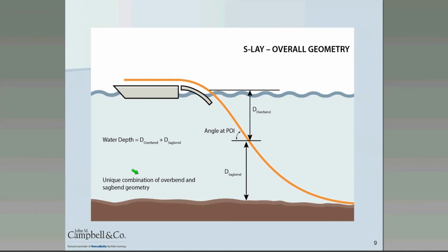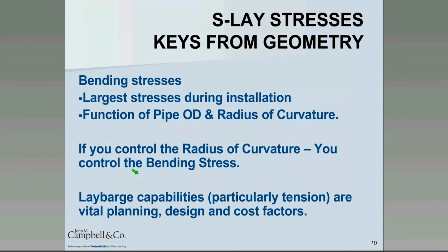Well, first of all, bending stresses during installation can be some of the largest stresses that you'll actually see in the pipeline during that period of installation. It's important to remember that installation is a very short period during the overall operational life of a pipeline. And often the stresses that the pipeline is subjected to during installation will be significantly larger than any stresses it will experience during its operational life. This has a direct impact on the design of the pipeline, selecting of wall thicknesses and weight selection, etc.